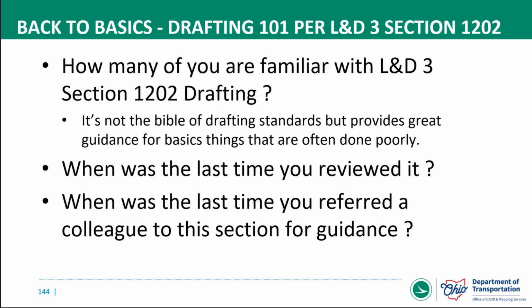These are the recommended drawing scales that are in here. Obviously, there are exceptions, these are the recommended scales. Again, keep in mind that 1 to 20 scale is at 22 by 34. So you're going to see that on your 11 by 17 it's going to be 1 to 40.